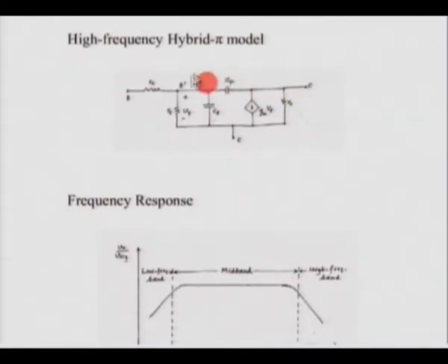So effectively when you analyze this particular circuit, we can represent this C mu as coming in parallel with this C pi, multiplied by approximately the gain of the common emitter amplifier. Now the typical voltage gain of a common emitter amplifier, let us say, would be about 100 or so. The value of C mu is typically about a picofarad or so, and the value of C pi would be approximately 10 to 12 pF.